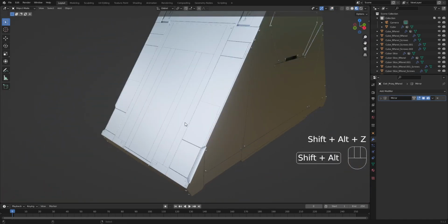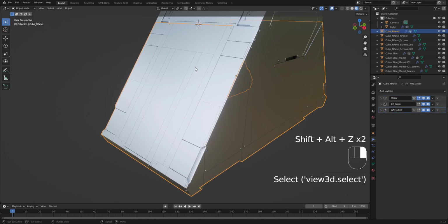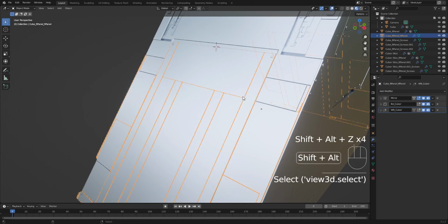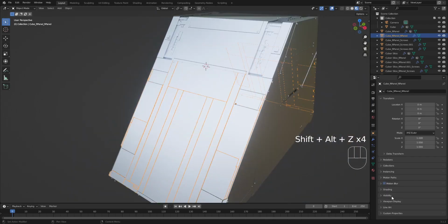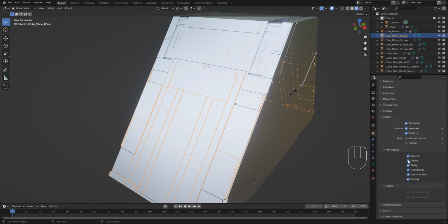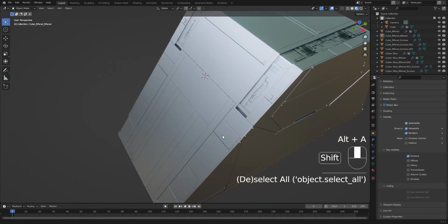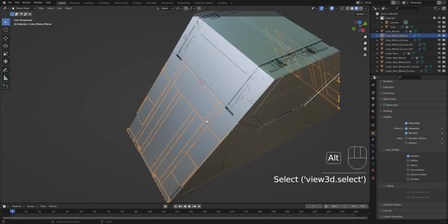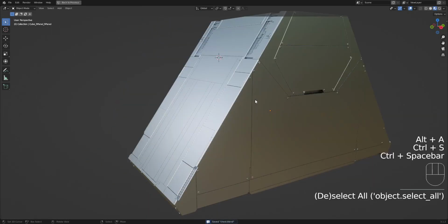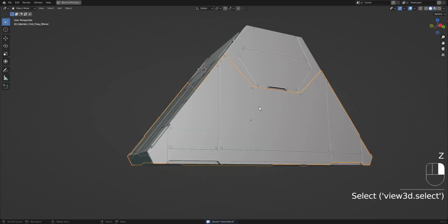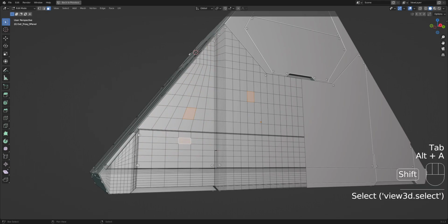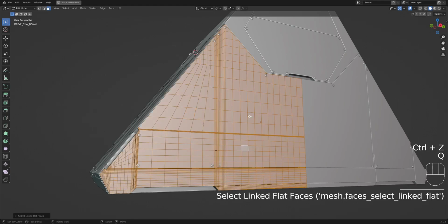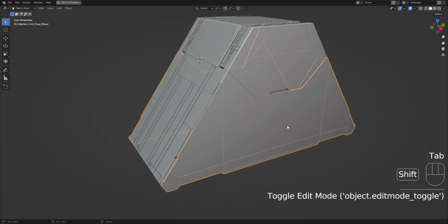But if you're using Cycles, you have to select the object, go to object properties, in the visibility go to ray visibility, and turn off everything besides the camera. So if you render this in Cycles, it will look like this object is part of the surface underneath, or they're the same object. So what we did is create another layer of detail without too much geometry.